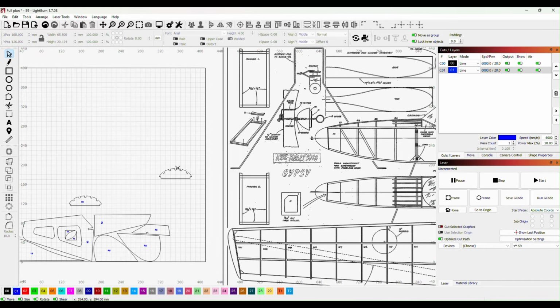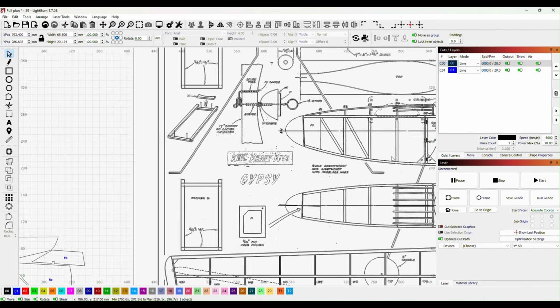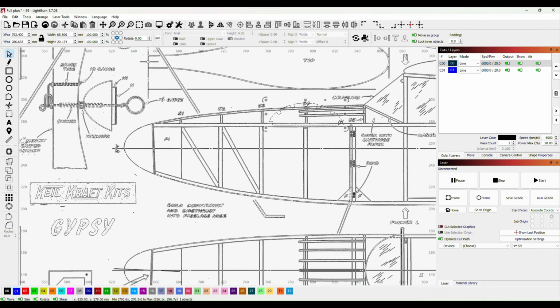Now with this one here, what we can do is bring it up to S4, and we can sit these edges right on the top of our longeron here. So I'll use Control and Shift and just move that down 1/10 of a millimeter at a time until I'm happy that it's on. And then, grabbing this top square, we can just bring the size down like that. Now that's shrunk the height of it.